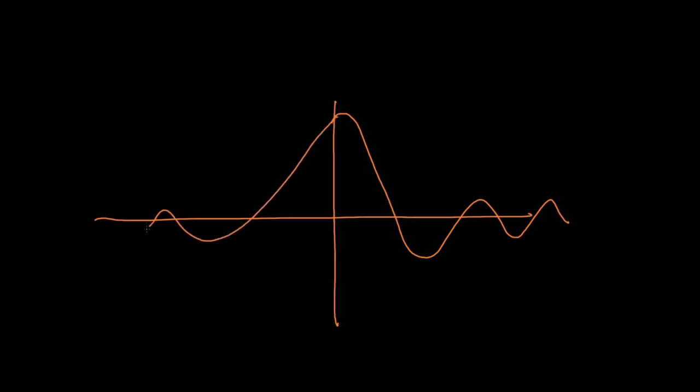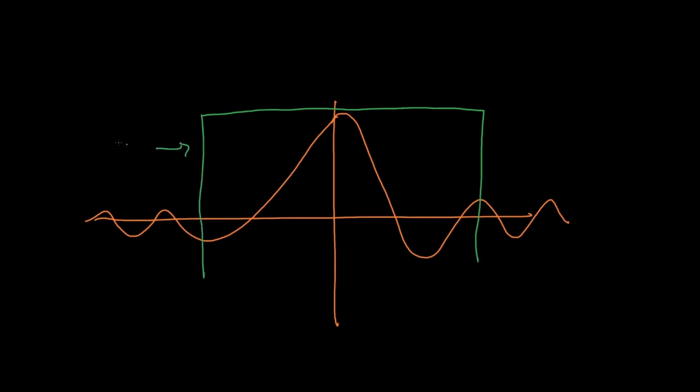Remember our impulse response of an ideal low-pass filter. The rectangular window is just a simple rectangle. That's our rectangular window. Now, a key point to understand is the only parameter you can change with the rectangular window is how far it goes for, how long the window is.